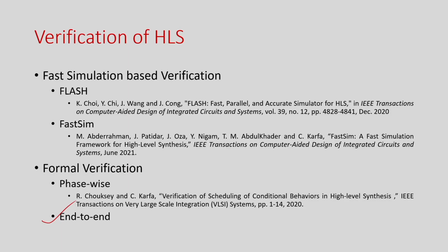There are two ways we usually verify: simulation or formal verification. In the context of formal verification of high level synthesis, till now there is no automated end to end formal verification tool. It does not exist basically, a tool which takes the C code and RTL, without taking any information from the HLS tool, and just checks whether they are equivalent or not. So, that is still evolving, and we do not have any very mature tool there. Some papers have been proposed, but they are not robust enough to handle all kinds of optimizations that a high level synthesis tool offers.